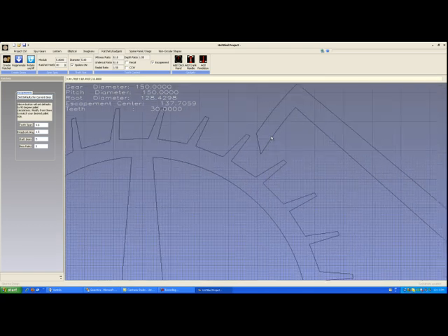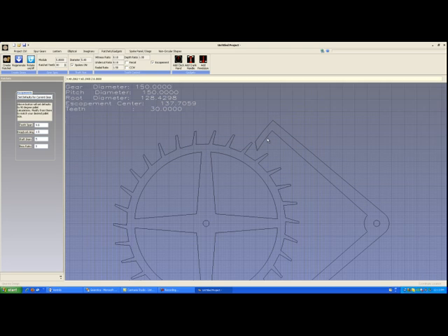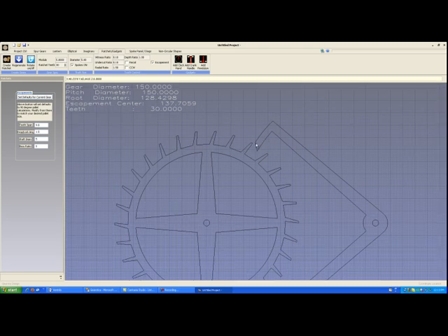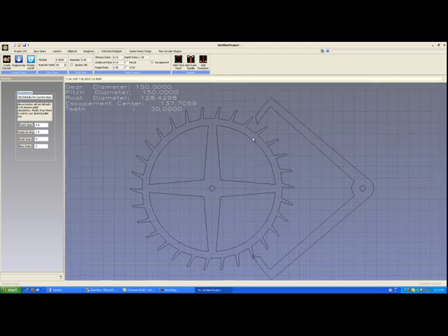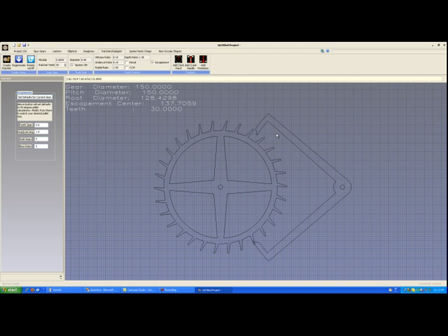It is a tilt. This is because the angle of the pallet has to be halfway between the tangents of the two circles. Here we have a pawl circle, and here we have a gear circle. The deadbeat is pushing in this direction on its tooth. We want the pawl to go in this direction, which is tangent to its contact point. Therefore, the angle has to be halfway in between those two extremes in order to have maximum energy transfer to the pendulum. The maximum energy transfer in an English type escapement is 50%.